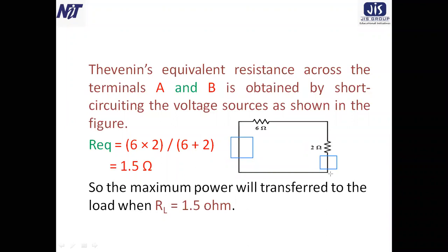Remember the Thevenin voltage, yes, Thevenin's theorem. For finding the internal resistance Req or RTH, we remove the voltage source. If a voltage source is there, just simply remove it, and after removing the voltage source, we have to short the line. So here we short this point. Short means we connect this point with a wire, a conductor.